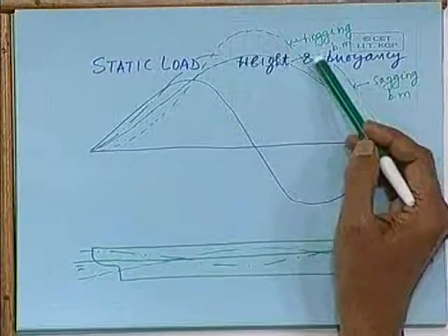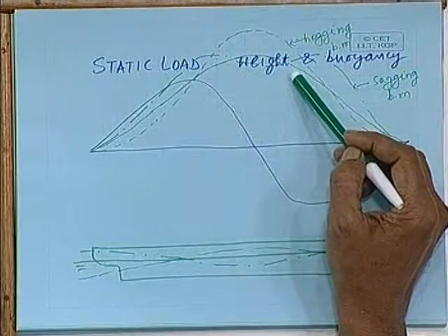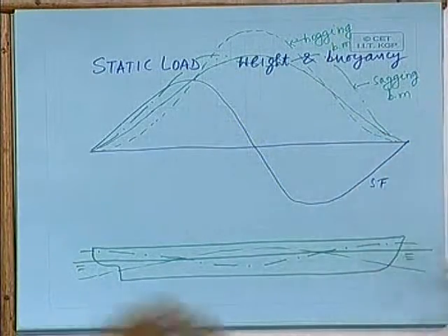shorter wavelength and varying heights. What I intend to impress upon you is that, therefore, even the static bending moment at any instant of time will not remain as shown by the full line here, but perhaps will vary somewhat between these two lines. Furthermore, during the life of the ship, if the ship experiences damage to a compartment and load goes in, then there will be further complications, similar to what happens in the case of unequal loading inside the ship.